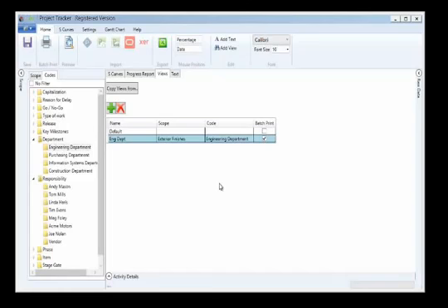Now also, once a view is created, next month we're going to do another export, and we don't want to have to recreate all these views every time. So what you can do there is to copy the views from a previous export, and they will come into this project, so they will automatically be set up as batch print. So each week all you really need to do is to do a new import of the data, copy the views from the master file, and all of our reports are already set up.